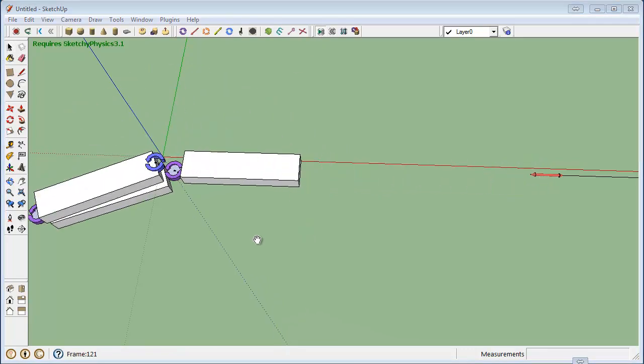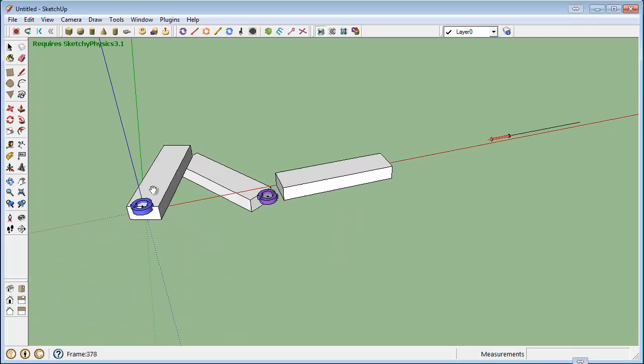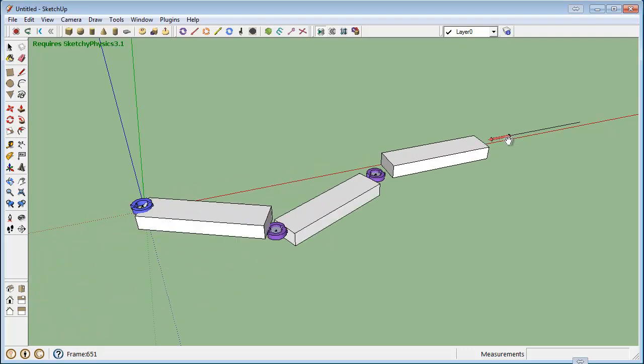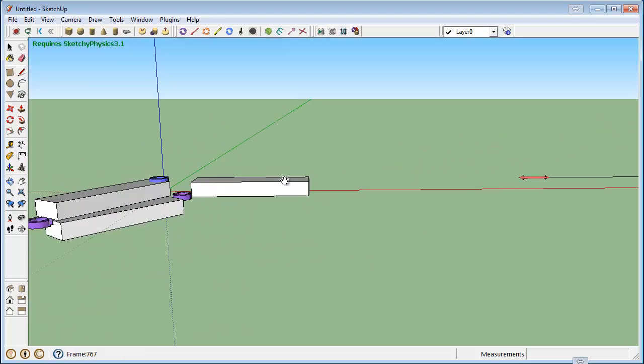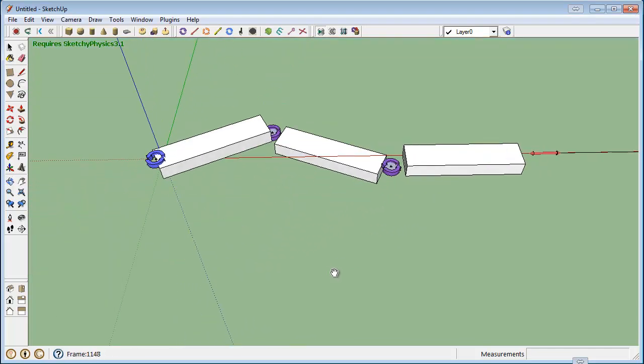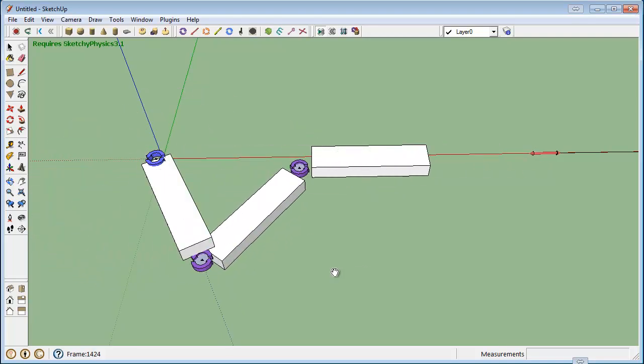There we go. So a couple of the tricks. One is properly making the hinges as separate entities, offsetting the solid blocks, and then also make sure the slider joint has a negative minimum and a positive maximum value.